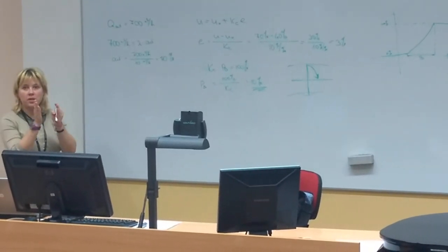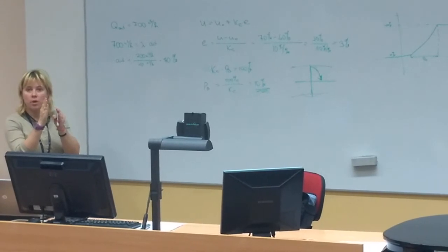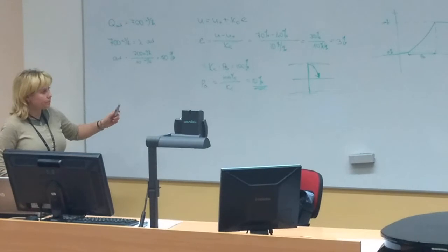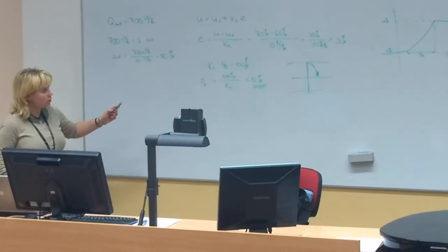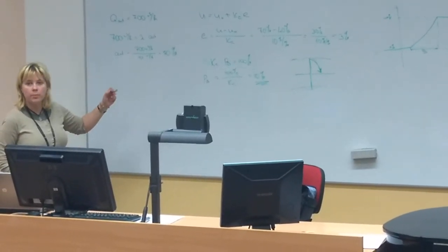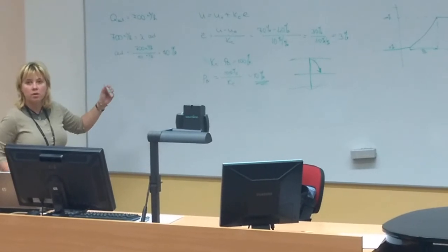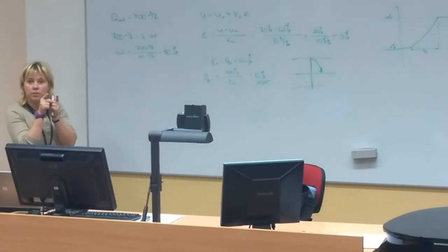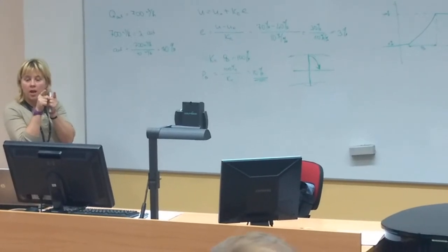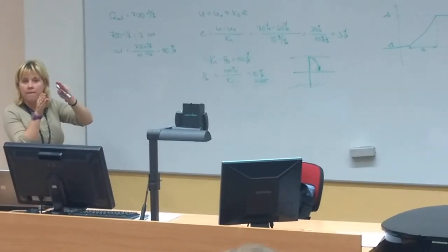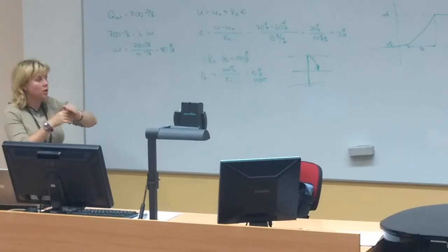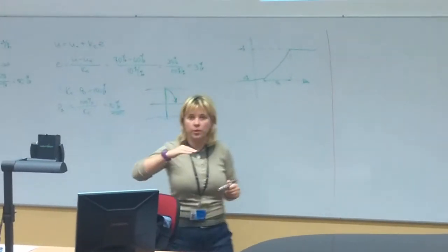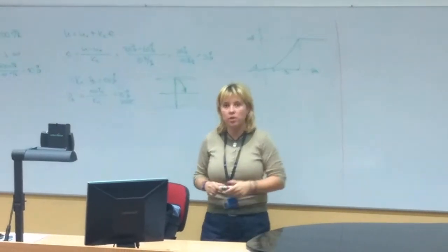So basically that means, depending on the set point, our output will be proportional to the error within that 9 degrees of the angle. And before that, we will have 100% or 0%, depending on which situation we are in.